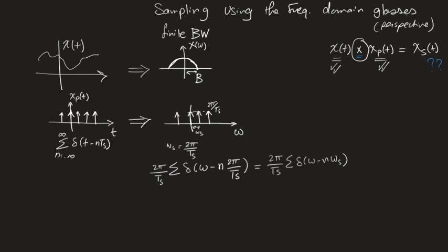If you go to the table of properties of the Fourier transform, you will find that when I multiply two signals in time domain, x1 of t multiplied by x2 of t, these are two signals, sorry, not convolution, multiplied, then in frequency domain it's going to be 1 over 2 pi times x1 as a frequency domain function convolved with x2 as a frequency domain function.